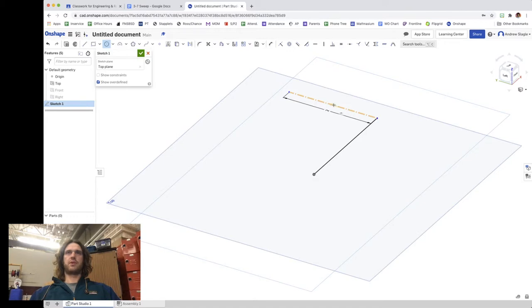I'm going to snap to the midpoint, and I'm going to trim off this inner half of that circle. So what that has done is it's created this perfect path that starts from the origin, and it comes out this direction, travels around, and then the sweep tool can actually, when it comes around this corner, change the planes that it's in, which is kind of exciting.